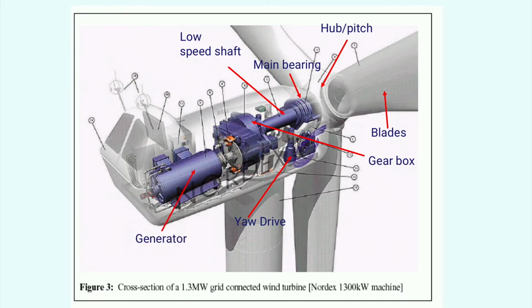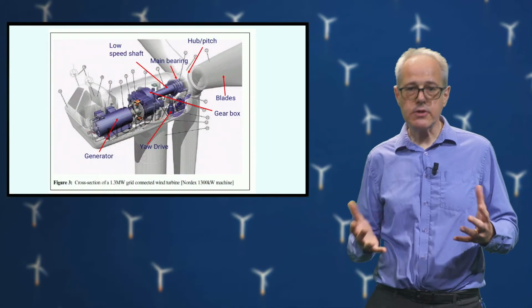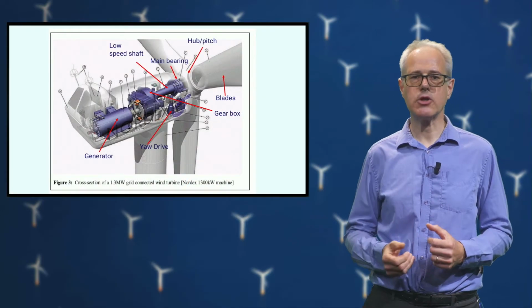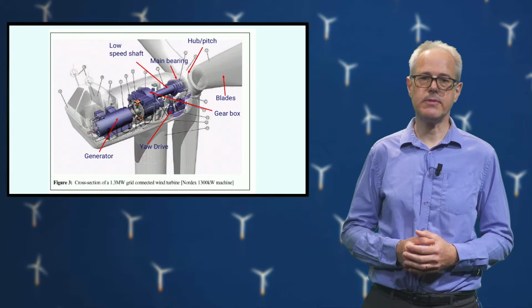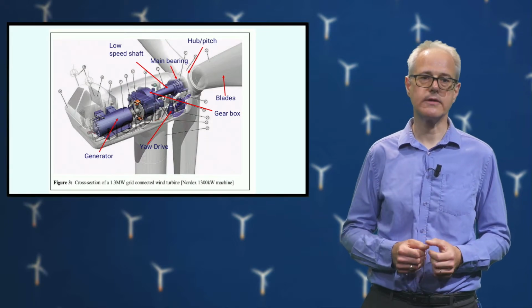The generator is a key component as it converts the torque into electrical power. The manufacturing tolerances required to maintain the very small air gap between the rotor and stator is small, but necessary for maximum efficiency. Such small tolerances mean that any eccentricities in the generator shaft can result in excess bearing wear or even rubbing between fixed and rotating components. There is also the added complication of electrical windings which can get hot, leading to possible damage if cooling fails.